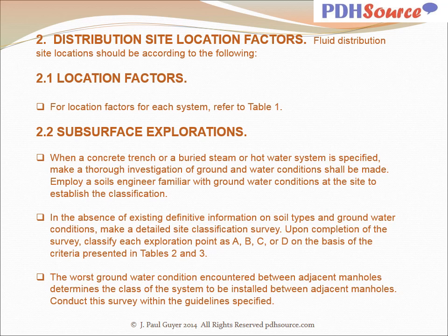Fluid distribution site locations should be established according to the following. Location factors, refer to Table 1. Subsurface explorations. When a concrete trench or a buried steam or hot water system is specified, make a thorough investigation of ground and water conditions.